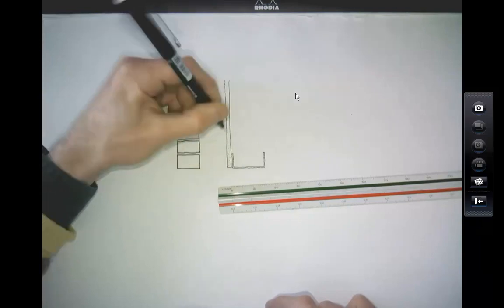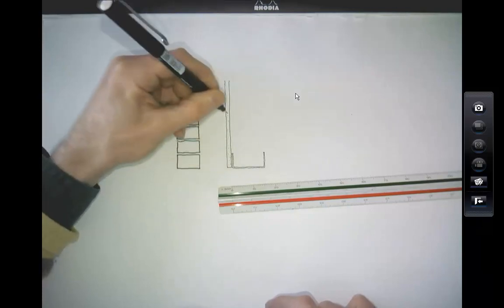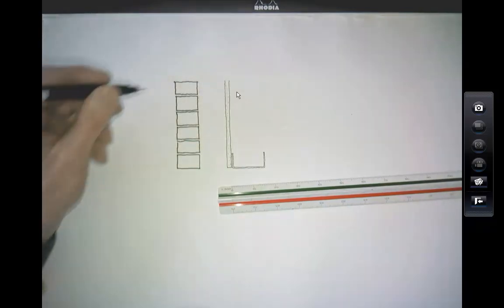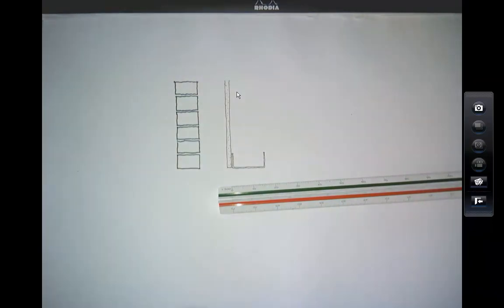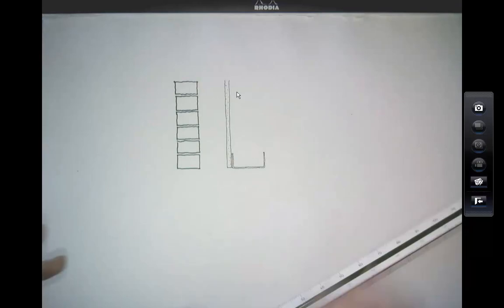Okay, and that's replacing that more old-fashioned blockwork inner skin. Now, there's nothing wrong with blockwork inner skins, and if your contractor is happy to use blockwork, great. It's really good and robust. Great for fixing too, but normally it's not cost effective.